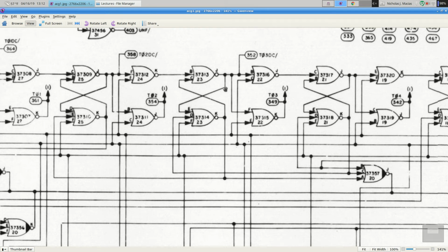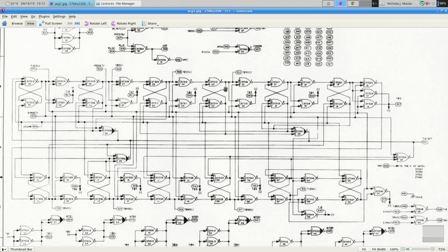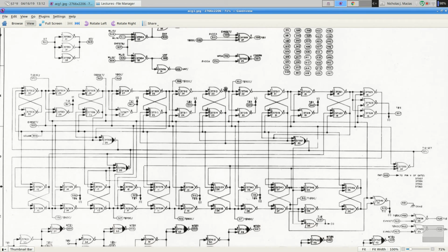But this was the memory part of this particular circuit, and it could remember voltage levels, logic 1s or logic 0s. So that's how they built the memory. Is that still how memory is stored? That's how static memory is stored. It's a very fast way to store and retrieve memory, but it's really expensive because you need 2 of these gates to store 1 bit.